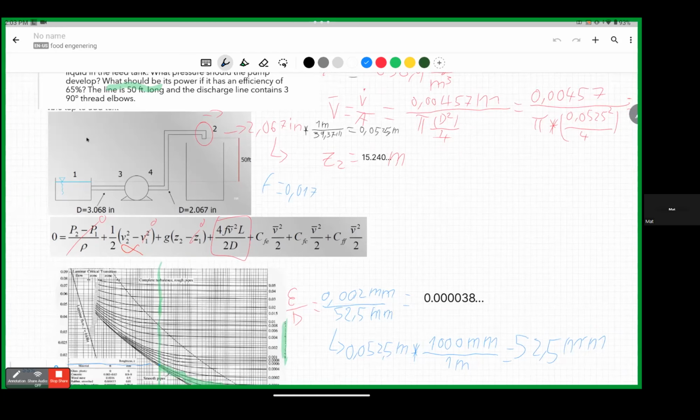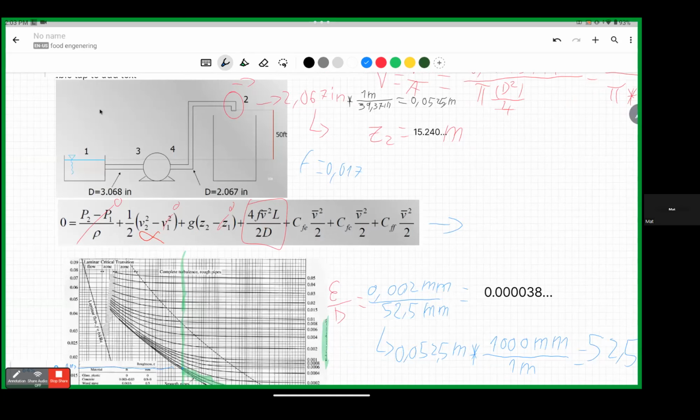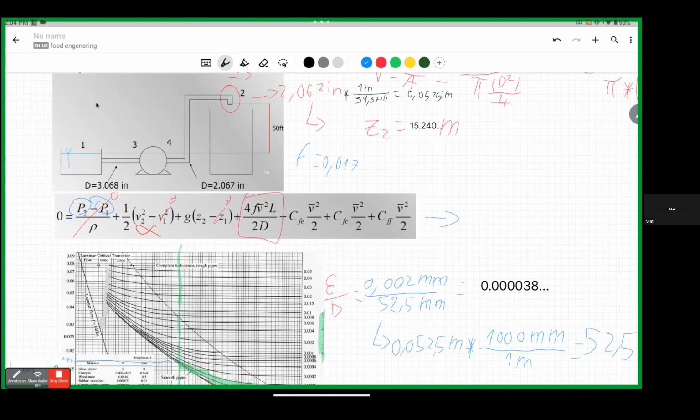Okay, like we were saying, this is the next part of our exercise. Remember, the pressure will be zero because we will have atmospheric pressure at P2 and at P1. Atmospheric pressure tends to zero because you don't have the water column or exit pressure at the output of the pipe. Because you don't have those two pressures, you can assume zero. That makes everything easy.